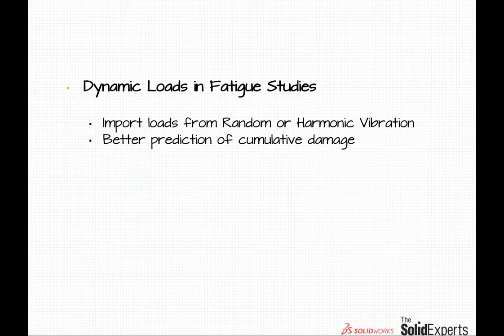So these are dynamic studies that we can import data to generate our fatigue studies. This gives us a much better ability to predict cumulative damage to our product. So this is a great way of enhancing our ability to verify the durability of our products.